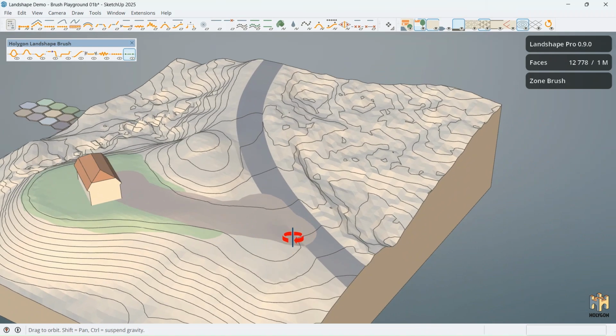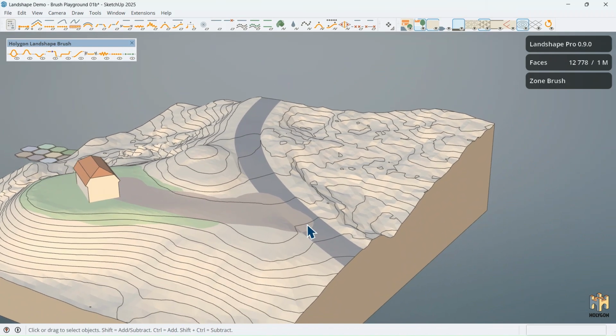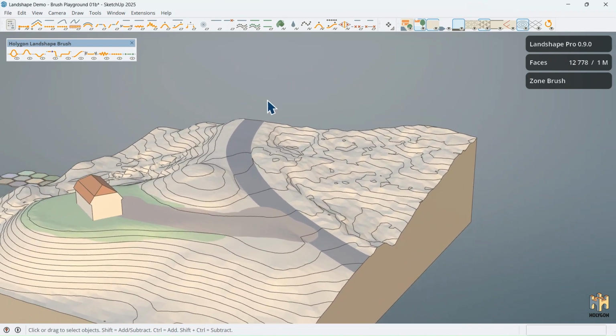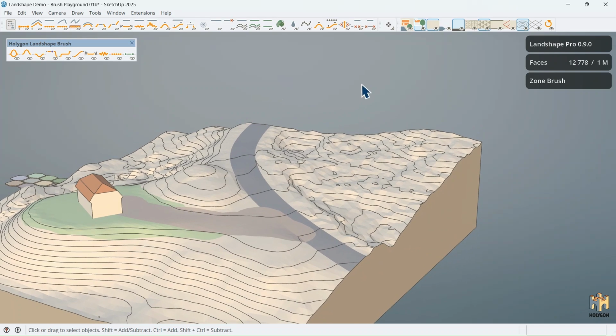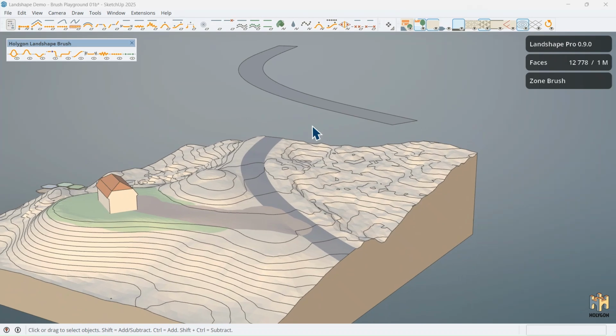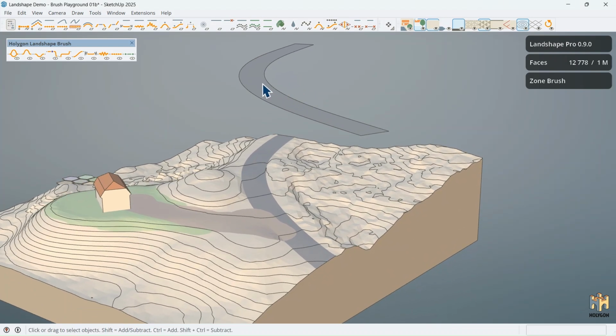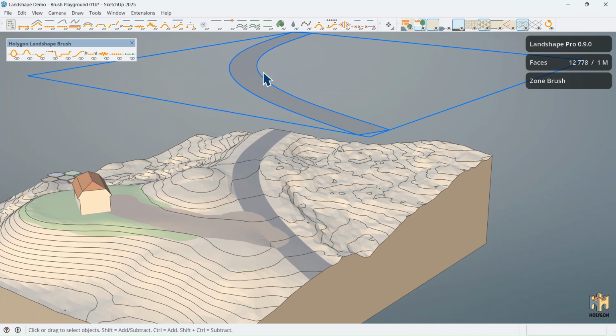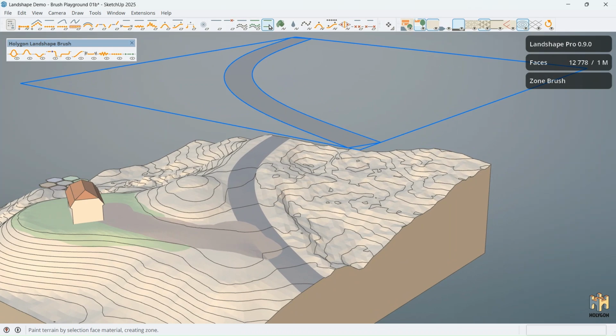I got this. And this doesn't look very pretty, so what I can do is that when I created the road, I got a control surface. It's on a tag. I'll turn on the control surface, select it, and go back and use the standard zone pick command. What it will do is read this face or surface and project it down to the terrain.